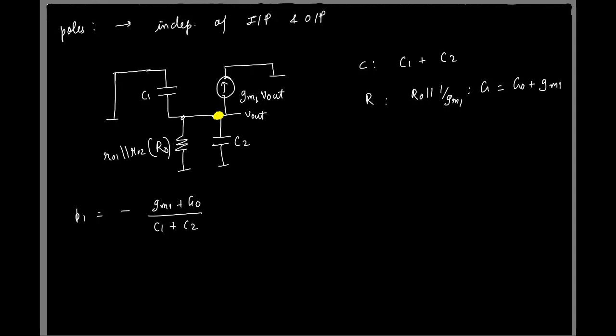Yeah, that's the deal. See, it turns out that without going into a lot of details, the number of poles you have depends on the number of independent state variables, or the degrees of freedom. If you were to relate it to thermodynamics, it's the number of degrees of freedom. In circuits, the state variables are basically those that have memory. And in circuits, what elements have memory?